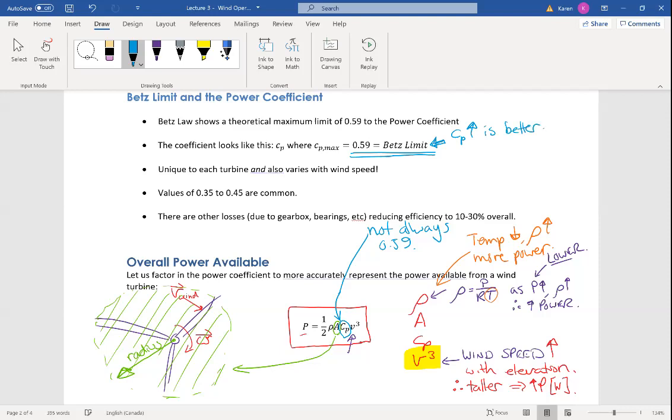But if you look at the derivation of the Betz limit, it'll show you that physics governs this. Basically, the coefficient of performance is like a catch-all constant that mathematically describes the friction and things like that, and the efficiency limitations in creating power out of the velocity that is given to us over this cross-sectional area at a certain density.